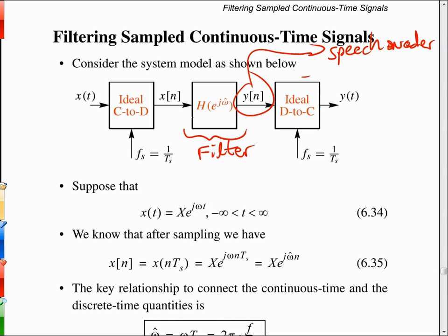So the speech gets compressed down to around 10 kilobits per second, and then it gets sent out as digital data. That digital data gets impressed upon an analog-based carrier signal in a microwave frequency band. Say it's either at 900 megahertz or around 1800 megahertz if it's the PCS band for cellular telephony.